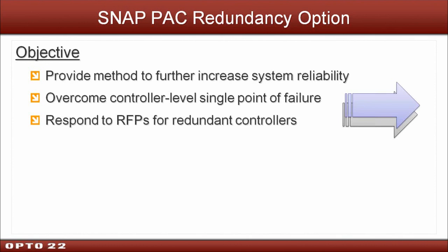And by that I mean we've placed a lot of processors within a system. So you have a controller processor, and you have processors in your I/O systems as well. To a certain degree, that inherently provides a level of reliability you might not find in a traditional PLC system, where it's normally a single CPU combined with essentially remote dumb I/O that's not processed.